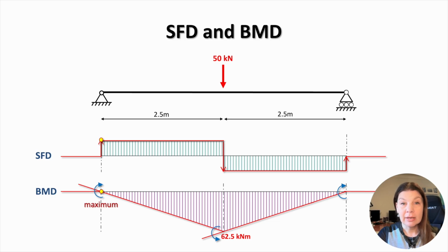The bending moment diagram is drawn on the tension side of the beam. As you can see, all the beam is in sagging bending. In addition, the bending moment diagram has three extreme points at the breaks caused by the reaction forces and the concentrated loads. These points occur where the shear force diagram crosses zero. At the left support, the shear force diagram crosses zero by moving upwards, and therefore the bending moment diagram develops a maximum at this point.